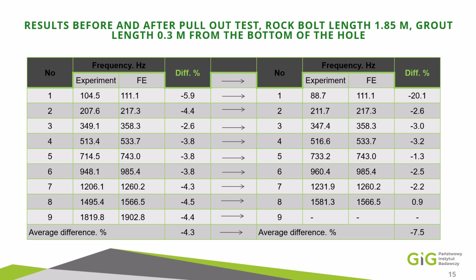Pull-out test gave us information that even such a length of grouting is enough for acceptance levels of that pulling out test. So it means that really this grout is quite strong, but it means that we can't check if that rock bolt is fully encapsulated using this method.